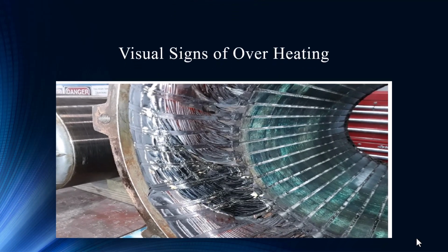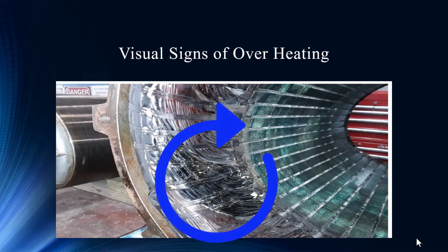And then just visual signs, right? Yeah, heat is a negative thing. It destroys the insulation. We have classifications for insulation, Class B, Class F, Class H, and when you exceed it by a certain temperature, 10 degrees Celsius, you kind of reduce the life of that electric motor by half. Oh, yeah. I mean, you look at this and you're a little surprised even that the resistance to ground we had was as good as it was.